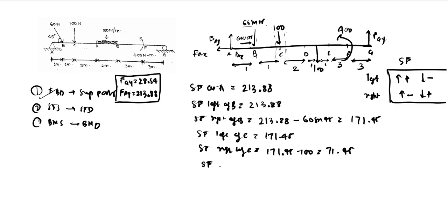Then we have shear force at D, which will be 71.45 only. We have shear force at E, which will be 71.45 minus 100, which is minus 28.55.